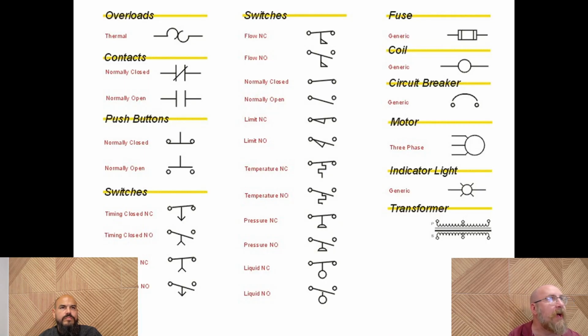They're still around, but they're less prevalent because oftentimes now we're hooking these things up with analog signals and we're just generating those switching functions digitally, like inside the PLC. But a lot of these symbols are where a lot of PLC comes from. If you look at the contacts up there, the normally closed versus normally open contacts, that's what we see in PLC programming, right?